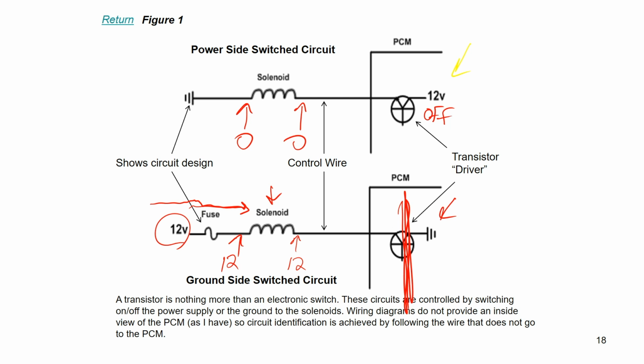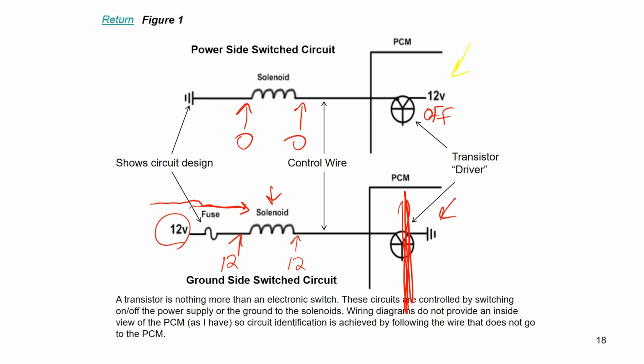So that pressure is going to come through this resistor. Doesn't matter what it is, right? 10 ohms, 100 ohms, 1,000 ohms. What if it's 1,000,000 ohms? There is a variable. And where's that drop coming from? My meter. Very good. So you see, we plug this in again. Meter can cause a drop if that resistance is too high, but in a sense, we could just say any resistor, any control, you're going to have 12 and 12. You're not going to have a voltage drop. No current flow equals no voltage drop. Everybody comfortable with that? 12 and 12. Normal circuit off voltage is 12 and 12.